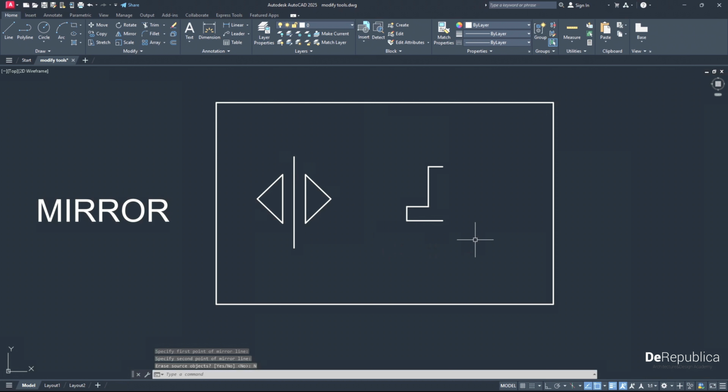One more example on the mirror command. Select the object, mirror, specify the first point, specify the second point, and so erase source object, no. We get a perfectly mirrored object.